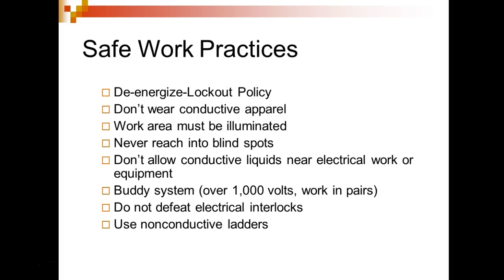Use non-conductive ladders. So when our last electrical instructor was here, he bought all these nice metal ladders, 4 of them. And we can't use them anymore, so they had to go out and buy all the fiberglass ladders. We can't use the metal ones to work on electricity.